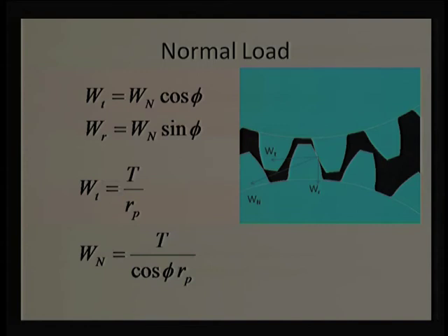So we need to design the gear pair in such a manner that, before losing the first contact completely, other pairs should start contacting. Then only the smooth transition of the movement will occur, and a smooth transition of the power. From one shaft to the other shaft, power can be transmitted when there is more than one pair of teeth in contact.